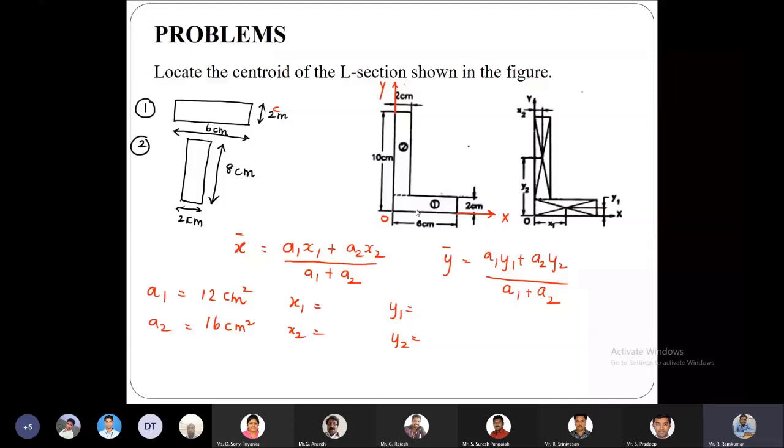For finding y bar, let us use the formula y bar equals V1 y1 plus V2 y2. Here a sphere is placed above a cylinder, both are solid objects and we don't have any cavity, so we need not bother about subtracting terms. We can directly add the product of volume and y1 plus V2 y2, divided by V1 plus V2.